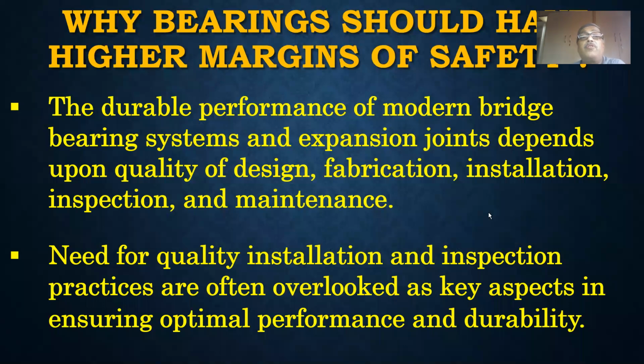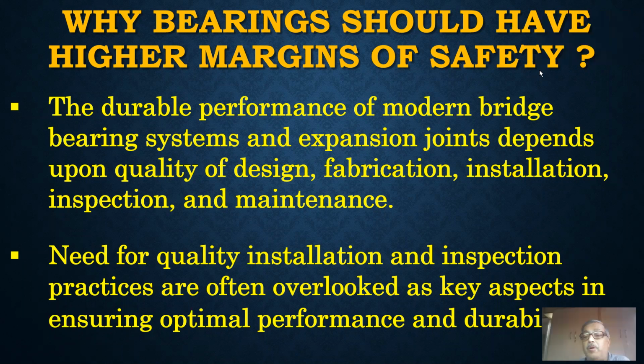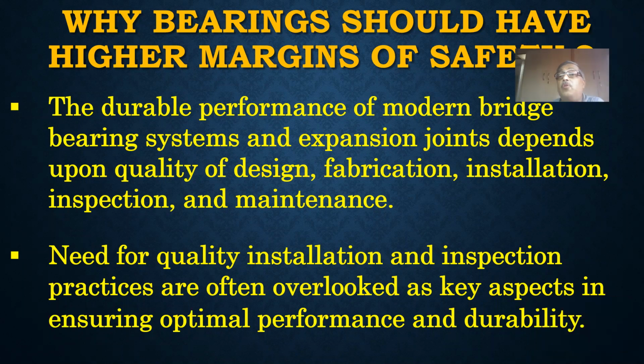Why should bearings have a higher margin of safety? I think this is an important point. Bearings are, as we all know, vital elements, and the cost of bearings is actually minuscule compared to the total cost of a bridge. Therefore, it is always important and prudent to be a little liberal in designing the bearings.